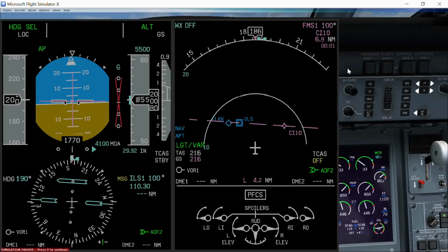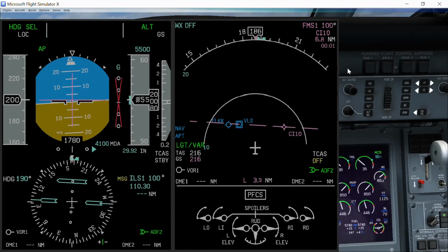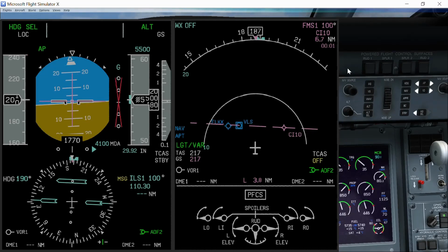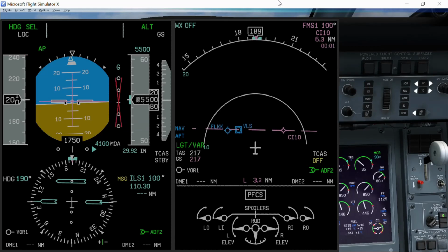All I want you to do here is to appreciate how the glide slope indicator will look when you are closer into the runway rather than further out. So let's unfreeze the simulator and see what's happening. Here we are approaching the centerline at 6.7 miles as shown on the top right of the MFD. And don't worry, as I said again, about this red cross on the ILS indicator. Normally it should be showing in reality, but it pops up when the system dictates that now it's running. There we go. Now look what is happening.